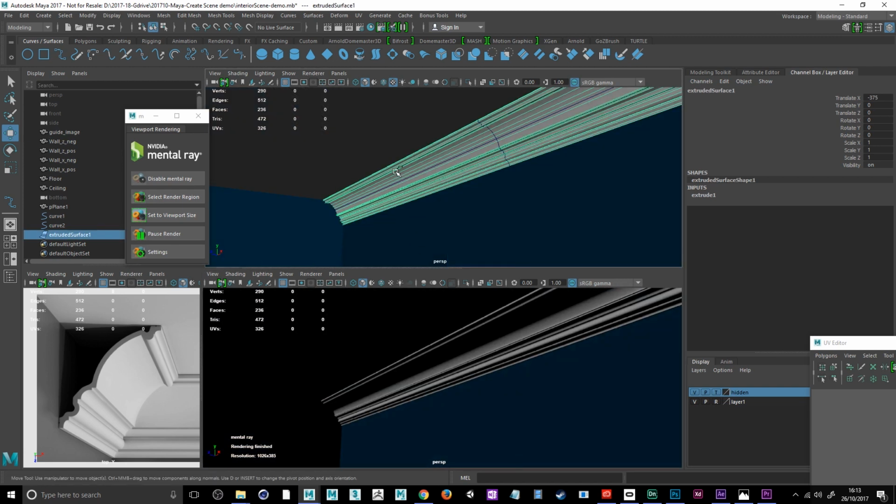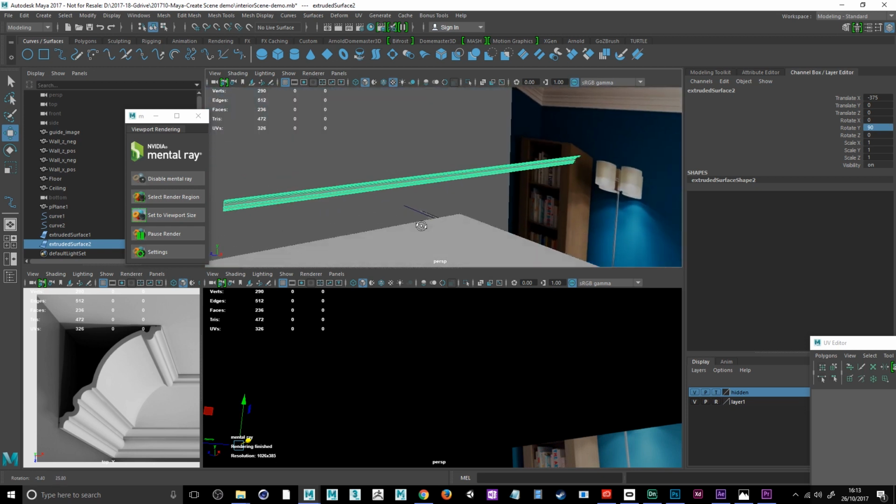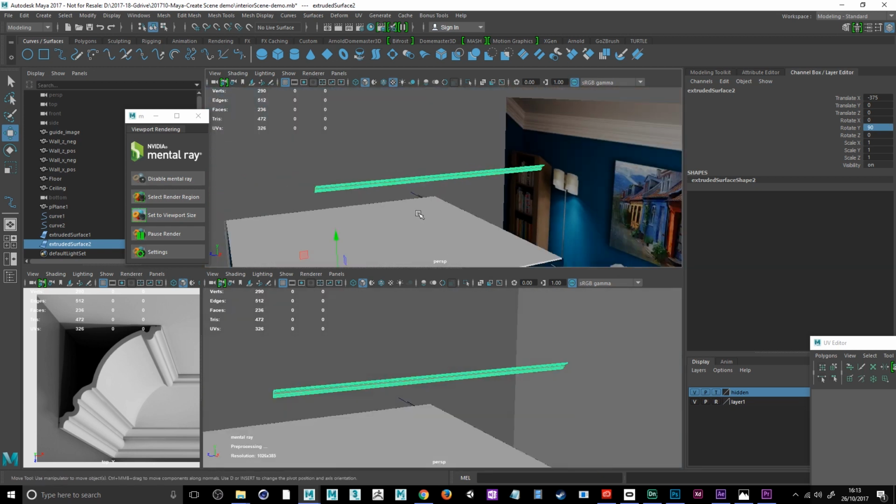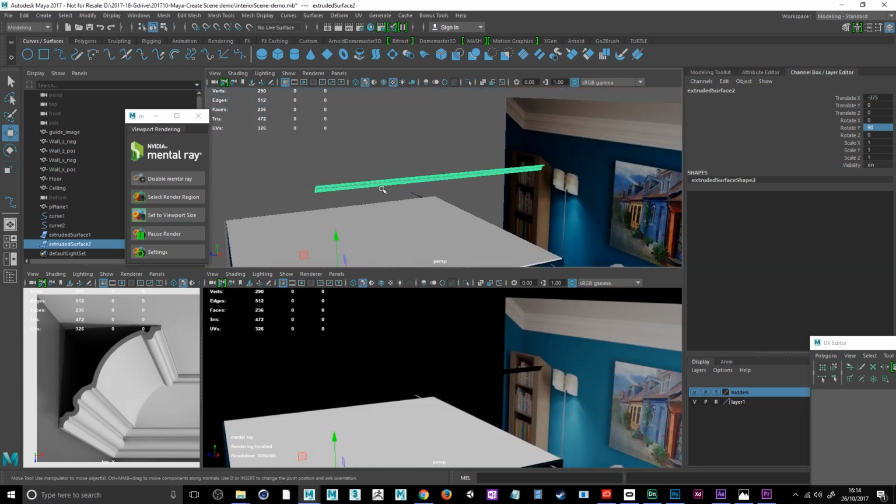So now it's a matter of duplicating that, which is a nice process. So I'm going to rotate around the Y axis, that's the up. I rotate that 90 degrees and press, I'm still in that window, type 90 degrees, press enter, click on the item there and press F. It should focus on that item, and I can see it's gone out a completely different way.